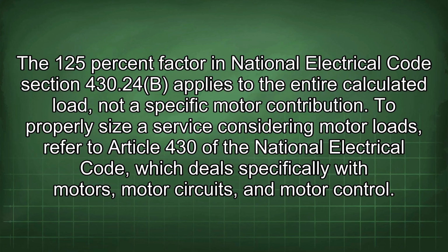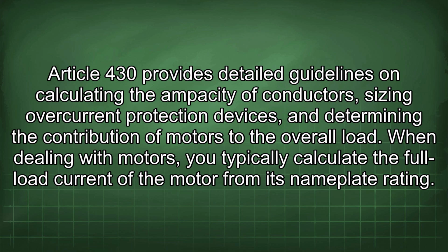To properly size a service considering motor loads, refer to Article 430 of the National Electrical Code, which deals specifically with motors, motor circuits, and motor control. Article 430 provides detailed guidelines on calculating the ampacity of conductors, sizing overcurrent protection devices, and determining the contribution of motors to the overall load.